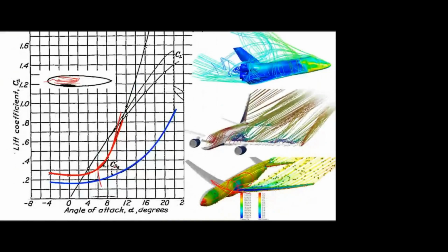Yes, sir. Okay. And here, position of wing in the axial direction or longitudinal direction. So from nose towards the tail, they are moving it. And you know, if it is near the nose, the disturbance will be less. So definitely this will produce minimum drag. And if you move in this direction, definitely the flow disturbance will also be high. So drag will be high.